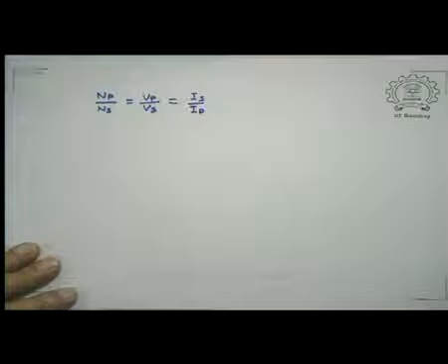So what it implies is that supposing we are using a step up transformer, then increase in voltage would automatically come with a corresponding decrease in current. And conversely, if you are using a step down transformer, then the voltage will decrease, but the secondary current will increase. So there is a trade-off between the current and the voltage, and depending upon what our usage is, we have to worry about that. So let me illustrate these with some typical examples.